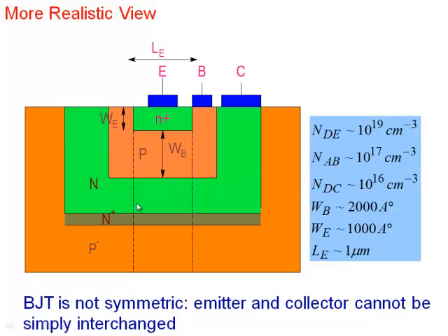The collector is over here. All this region is collector. And collector is lightly doped, 10 to the power 16. Could be higher also, could be 5 times 10 to the power 16, could be 10 to the power 17 as well. These things vary. Could be even lower doping. Alright, so that's the collector here. And so this is how a bipolar transistor actually looks.